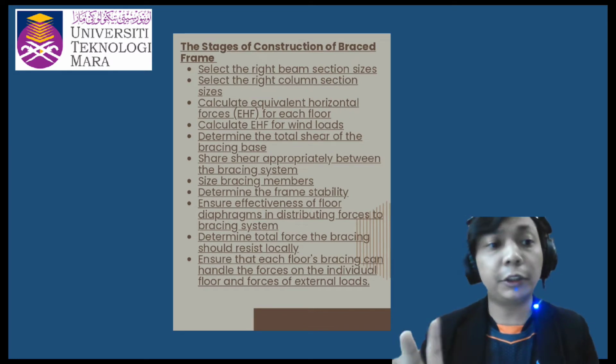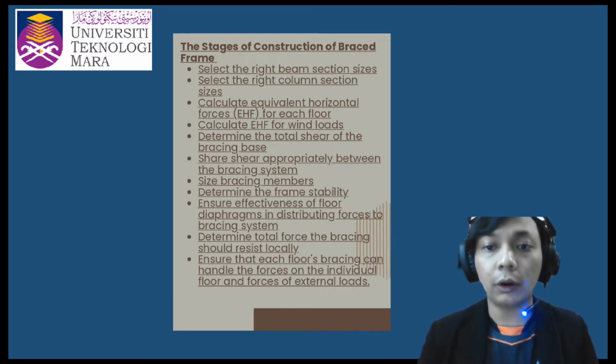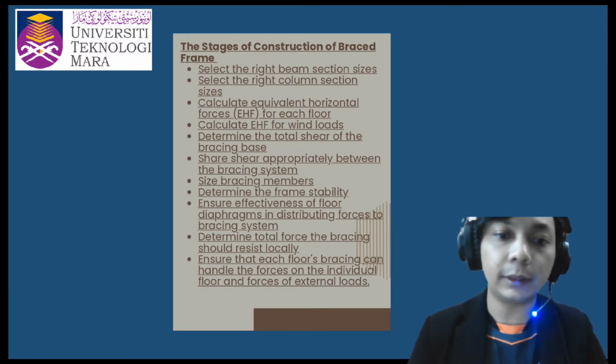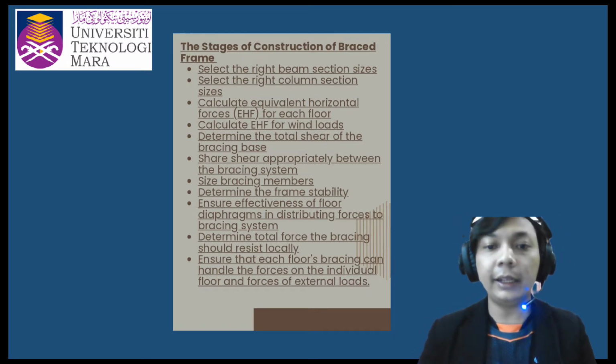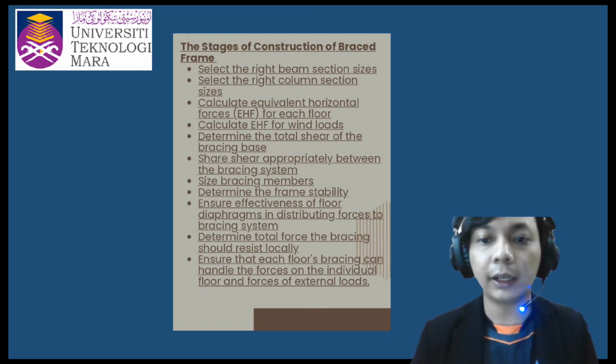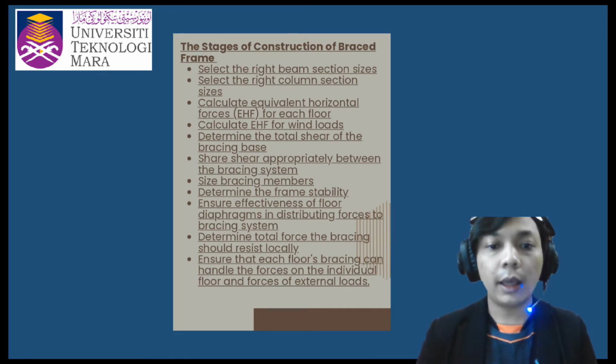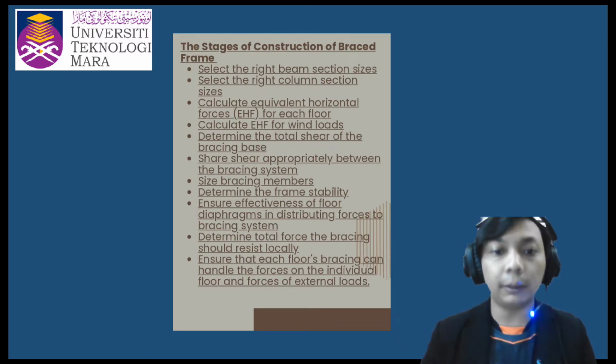With well-designed construction, buildings of less than 8 stories can be deemed stable. For stability, taller buildings require a concrete or braced steel core. Building designers bear a significant amount of responsibility for designing good bracing, and the contractor must subsequently guarantee that the bracing system is installed correctly.